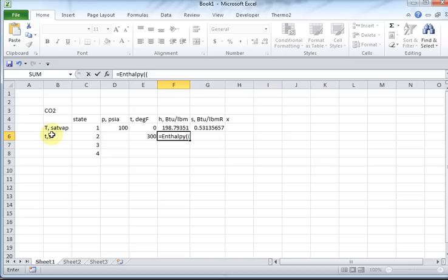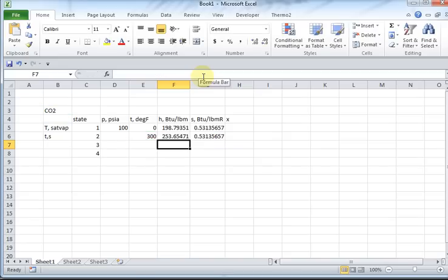Enthalpy as a function of temperature and entropy. I'm used to the syntax with the other software. I've first got to say what substance I have, comma, what units, temperature entropy, true, temperature entropy in English units, and there's my temperature and entropy value. And everybody, what do you think? Gonna work? It worked. Wow, that's great.